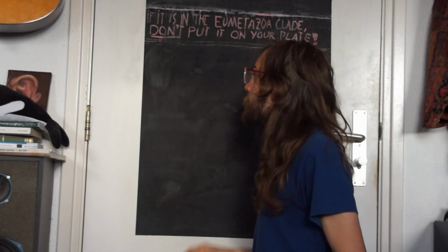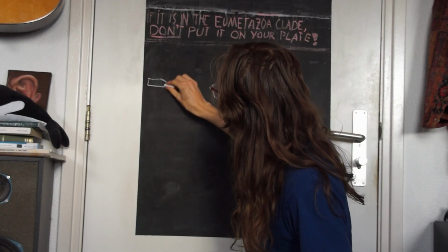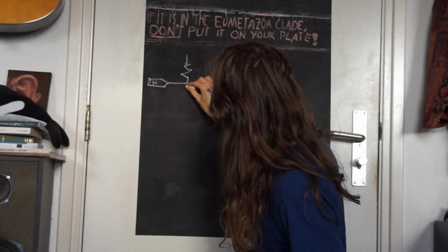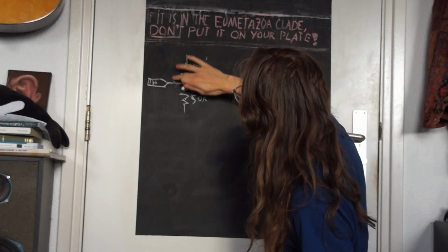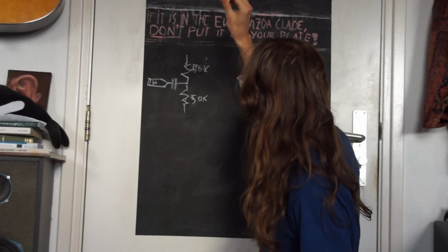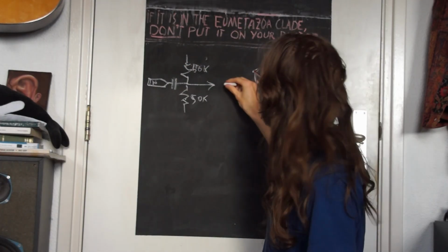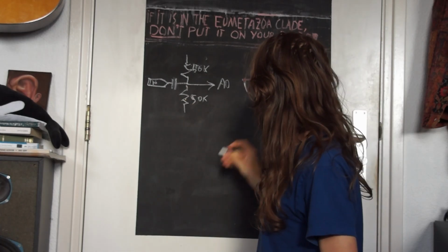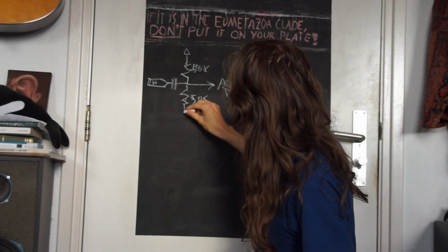So what do we have now? We have our guitar coming in. It goes into a voltage divider. And of course, it's AC coupled. That goes to the analog read pin A0 of our Arduino. And that reads our guitar signal. This goes to 5 volt, this is ground.